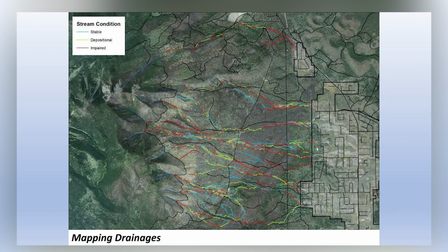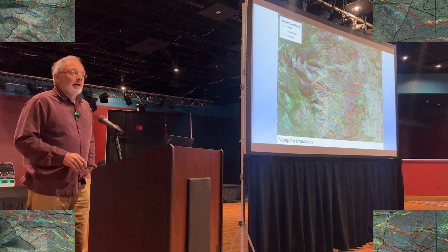They don't pass it very well, and so this is of use to us in the future. So here's just an example map of something that we created following the Schultz fire back in 2010. We visually assessed all of these channels, about 65 miles worth. Did it pretty rapidly. This was a 15,000 acre burn, and unfortunately, this is on very steep slopes, and all of this stuff down on the right side of the map there are houses.